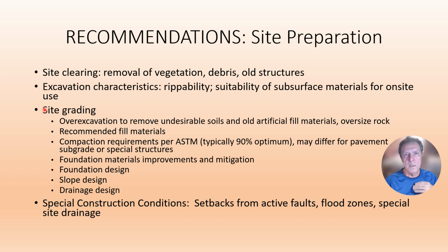As the site is being graded, you want to give them an idea of what kind of over-excavation is going to be required to remove undesirable soils, old artificial fill materials, oversized rock. What are the recommended fill materials which can be used for the site?